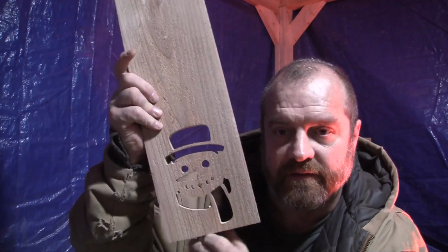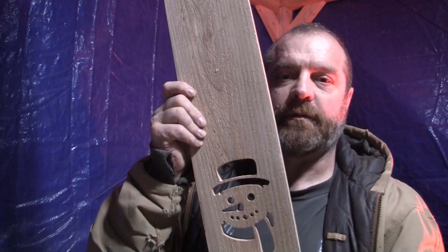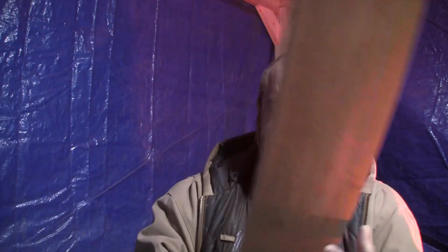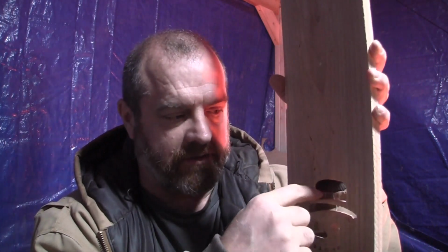Alright, so there's a little snowman head. If you can see it, put it on my black shirt. There you go. These are pretty cool. I like the way that Fusion 360 writes its G code, with the little spiral that goes in ahead of time. So you're always doing a climb cut with it. I know other applications can do it. I just like the way that Fusion 360 does it. So that's how you make a snowman head using Fusion 360.